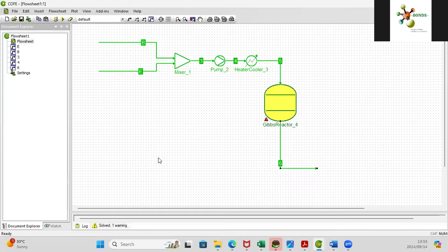Then the next step is we're going to look at your separation processes. This is where you need to decide what is the best way to separate your components. From literature, what I found is that they use distillation, and they do it in 2 stages. The first stage will separate your benzene, which will be sent back for recycle.